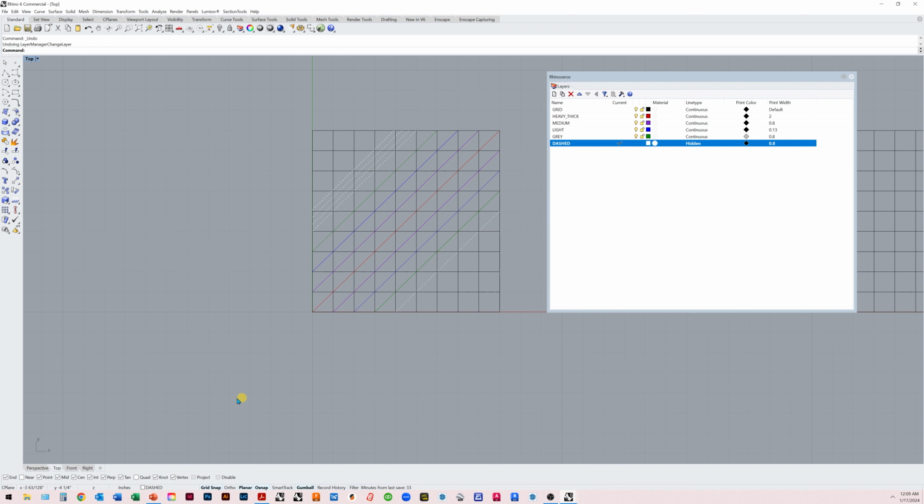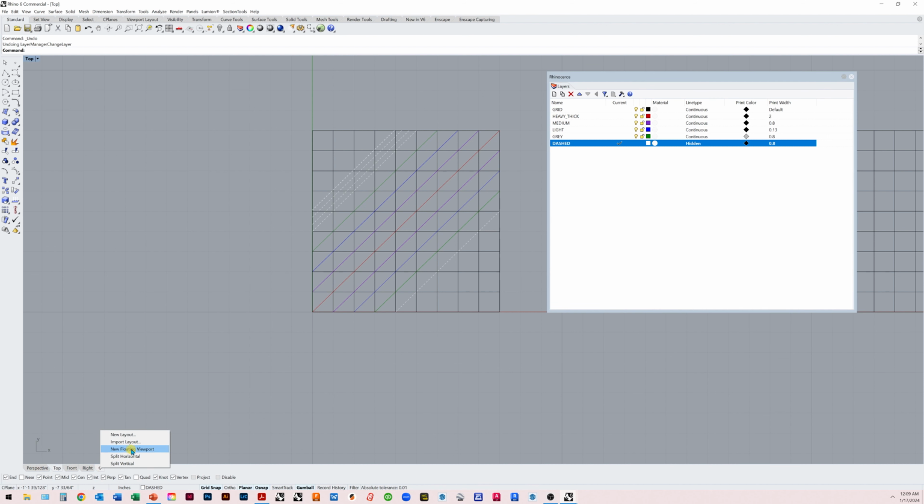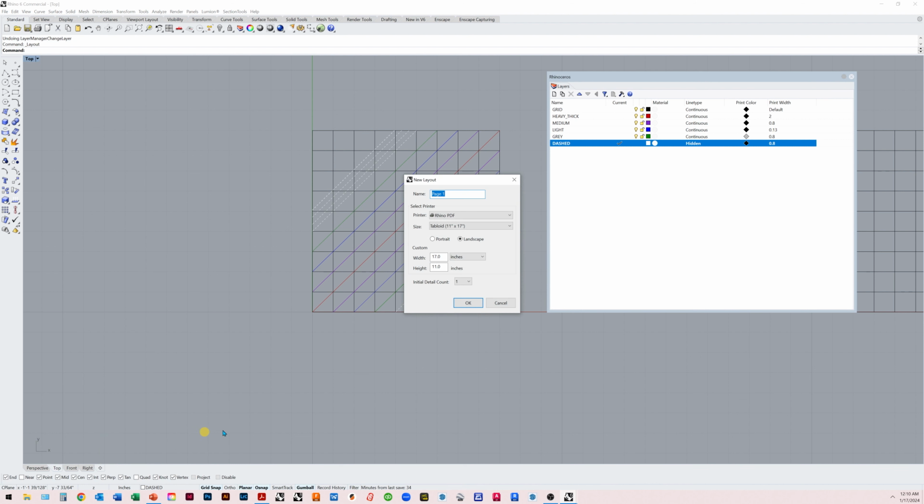The next step is to go in and create what we call a layout sheet. That will allow you to put your drawings onto an 11 by 17 sheet to turn in. Okay, so to create a print layout, you are going to want to go to the bottom of this sheet. If you go all the way to the right to this plus, these are your tabs you remember from the beginning. You can go in here and create a new layout. Then let's follow these steps.